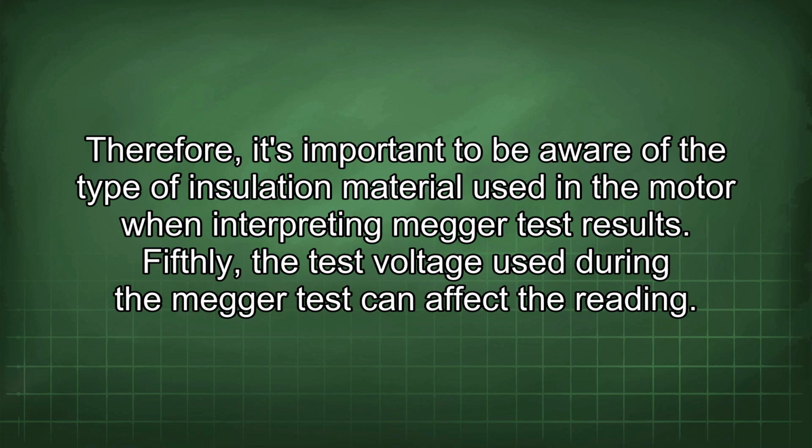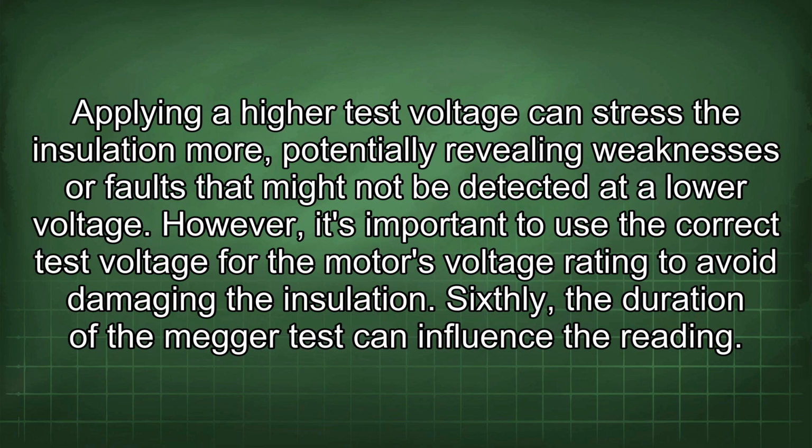Megger test results. Fifthly, the test voltage used during the Megger test can affect the reading. Applying a higher test voltage can stress the insulation more, potentially revealing weaknesses or faults that might not be detected at a lower voltage. However, it's important to use the correct test voltage for the motor's voltage rating to avoid damaging the insulation.